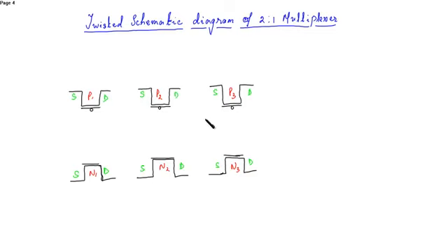We know the gate, of course, from here. In the transmission gate, we know very well that the gates are connected in opposite. So we have to draw the transmission gate. We have to draw the schematic diagram in such a way so that it will be easy for us to draw the layout. So we can connect from here.